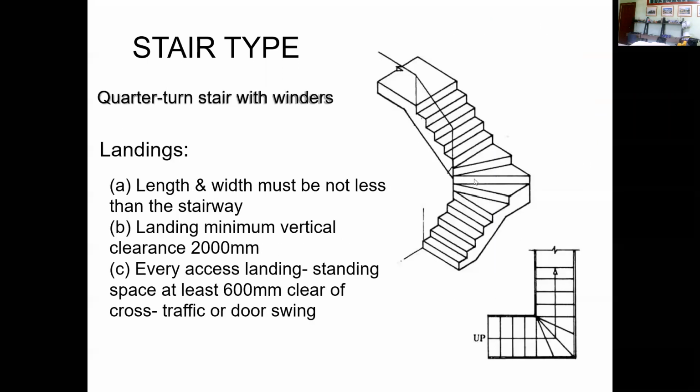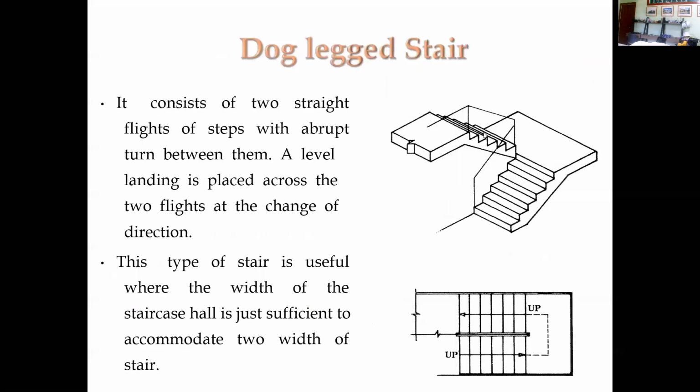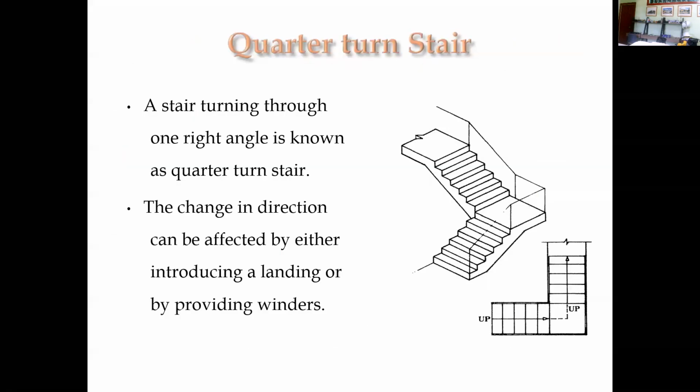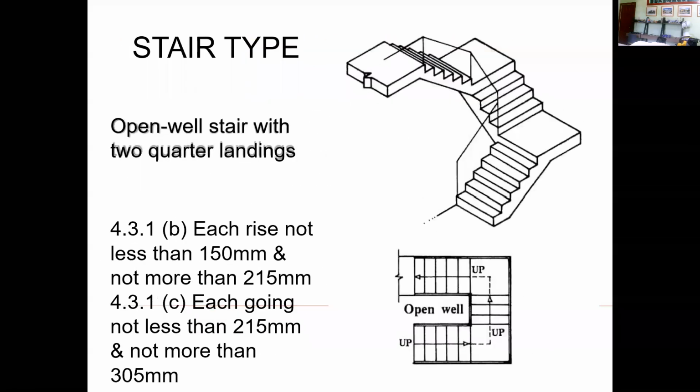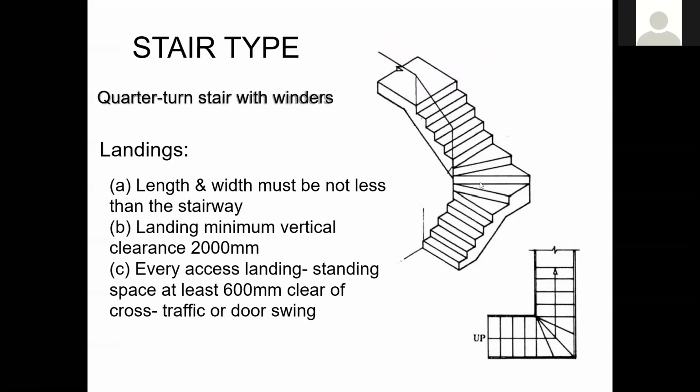So this is what you call a winder. This is the landing. You divide the landing into steps to make more steps. So these steps are called the winders. So this is another type of stair, the quarter turn stair with winders.